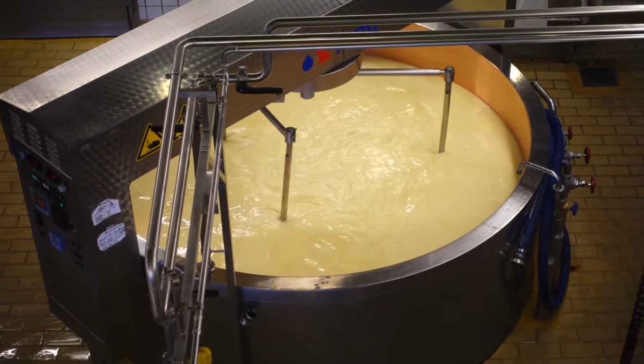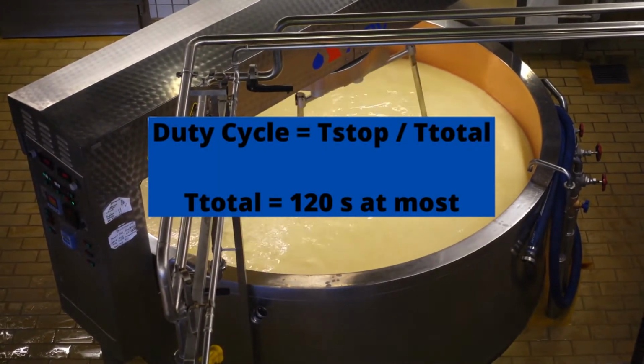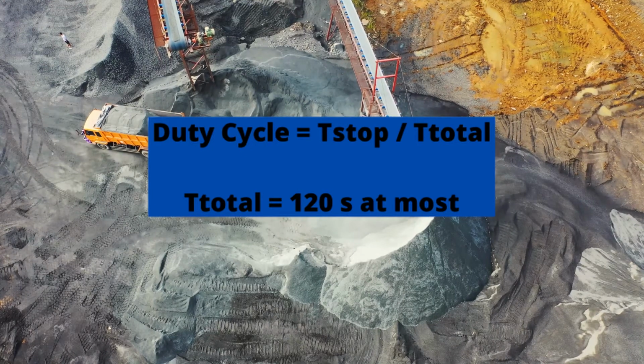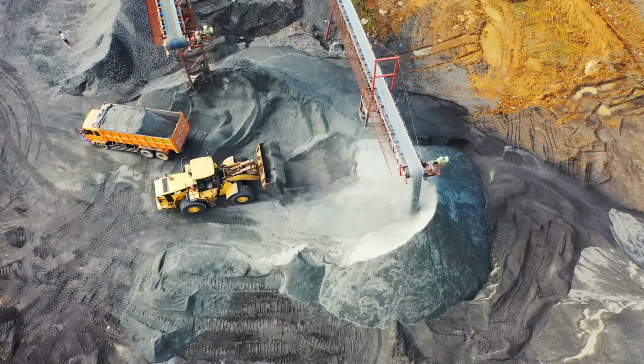To explain the duty cycle in more detail, this is the amount of time spent stopping versus the total operational time. It should be noted that the total time for a duty cycle should not exceed 2 minutes. This, in general, is the amount of time over which a brake can be expected to dissipate heat.